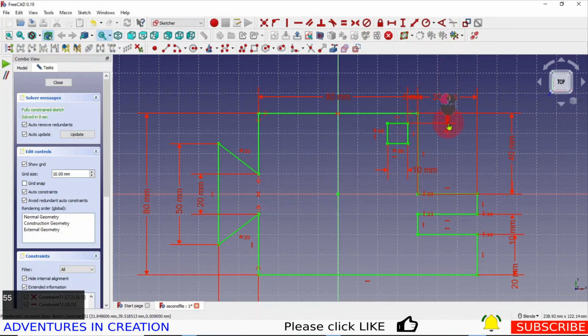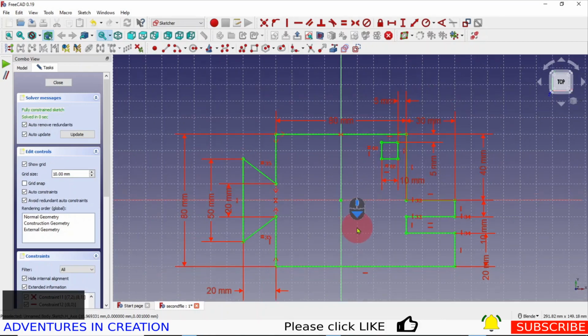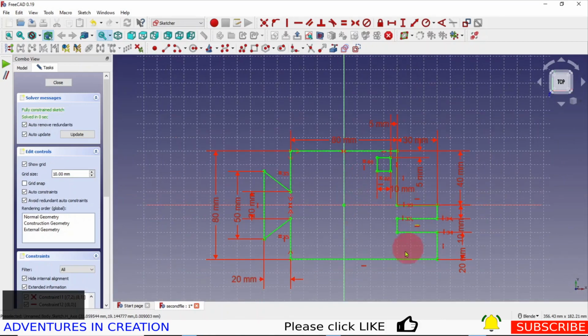And now you saw that the sketch suddenly went bright green. That basically means it's fully constrained. It says here it's a fully constrained sketch. That means if I grab this and try and move it, it won't move because everything is constrained. So we've told this sketch how to place these lines in a way that they can't be moved. If you notice, all I did was go through it methodically, took my time, kept the shape about the shape I wanted, and created that.